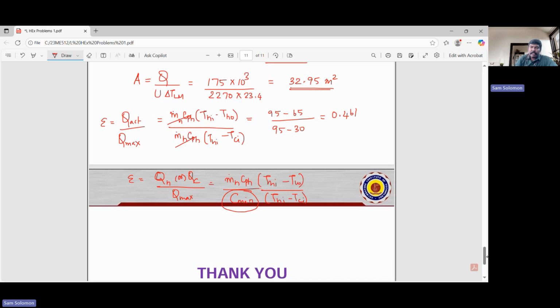So in a question involving this, always check m dot h CPH and m dot C CPC. Of these, which one is minimum? Take that and substitute it over here. So the minimum of these two values is supposed to be taken and substituted in this particular equation.